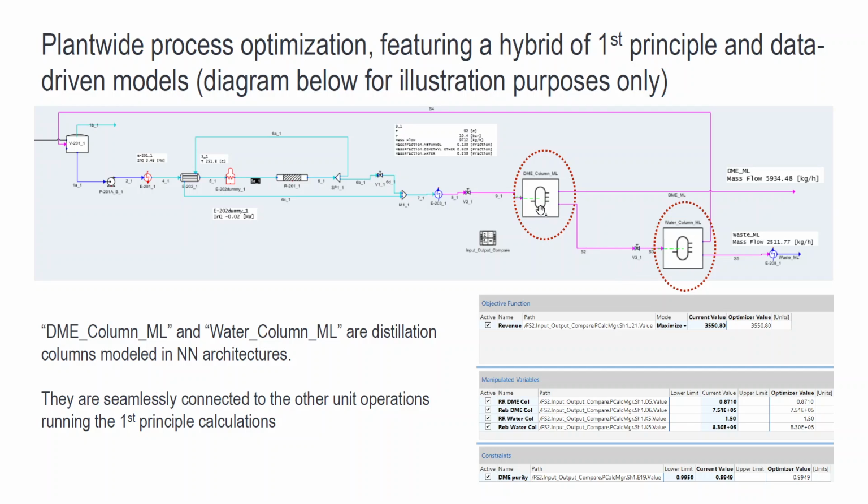But with this hybrid feature, the neural network is simply like a regression, so it's very easy to solve. If we have this type of configuration, solving it is much faster, and it's guaranteed to be solved, compared to the distillation column where we can find this unconvergent situation. So that's a tool that we can use: a hybrid between the first principle and some regressions to overcome the non-linearity and the recycles in the system. That's one example in this aspect.